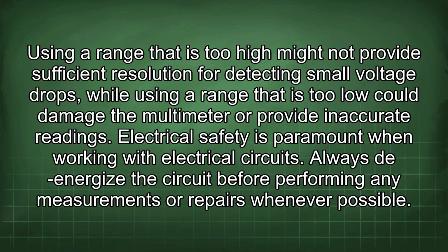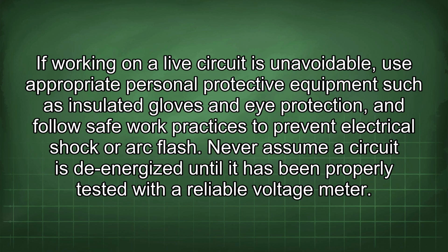Electrical safety is paramount when working with electrical circuits. Always energize the circuit before performing any measurements or repairs whenever possible. If working on a live circuit is unavoidable, use appropriate personal protective equipment such as insulated gloves and eye protection, and follow safe work practices to prevent electrical shock or arc flash. Never assume a circuit is de-energized until it has been properly tested with a reliable voltage meter.